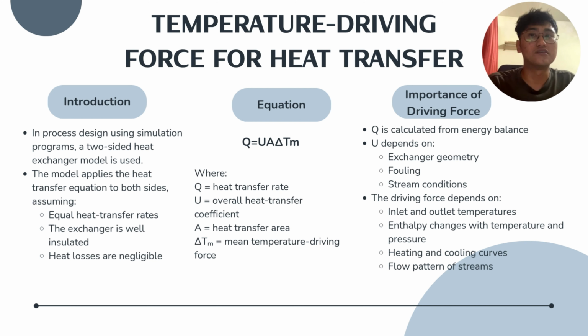For the equation, the fundamental equation used is Q equal to U A delta T M, where Q is the heat transfer rate, U is the overall heat transfer coefficient, A is the heat transfer area, and delta T M is the mean temperature difference, which is the driving force. This equation shows that the heat transfer depends not only on the equipment design but also on the temperature difference between the fluids.